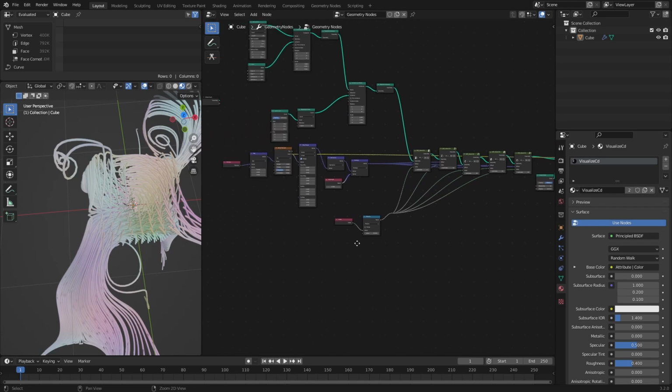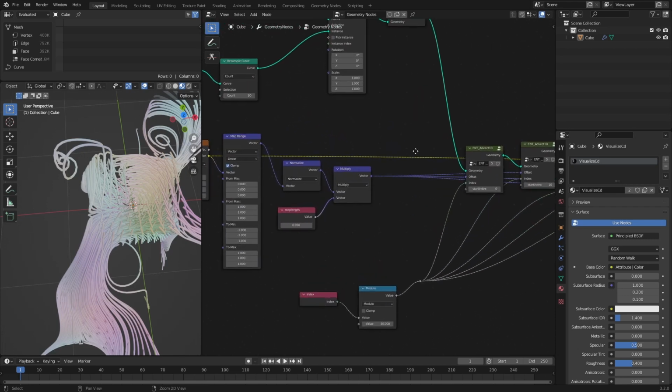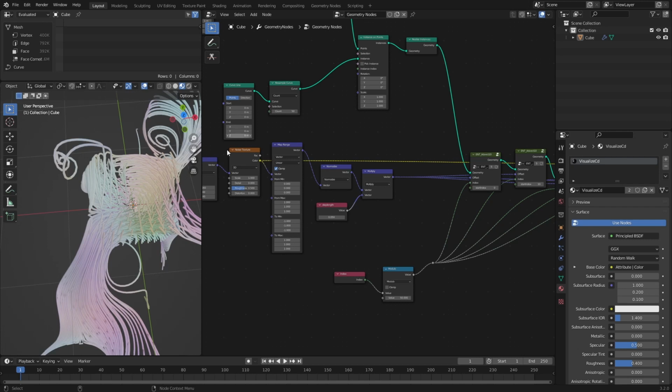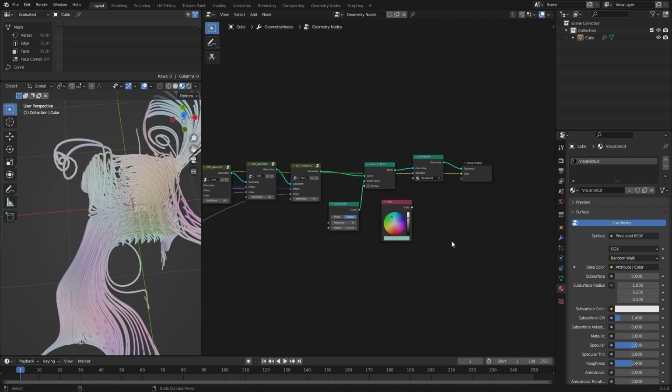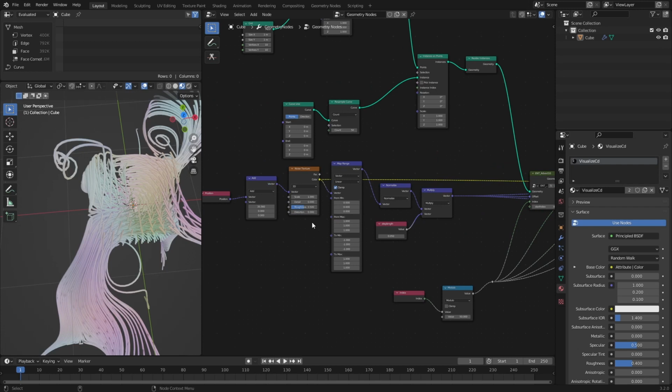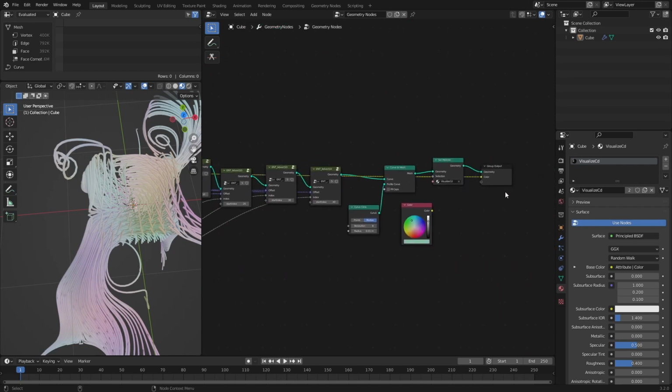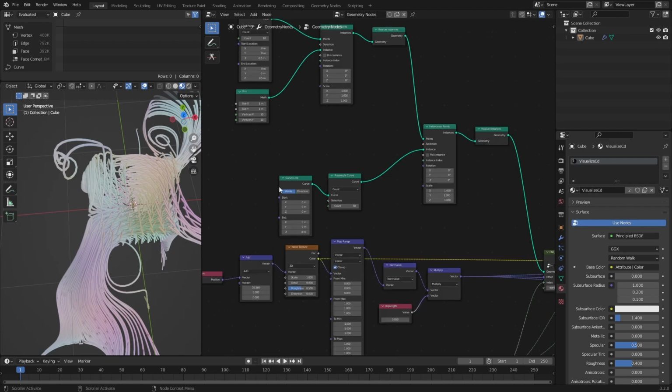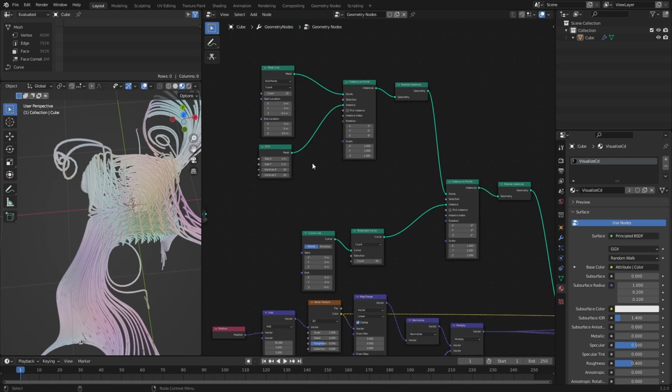To do this, we need a node that tells geometry nodes where to execute this color field here. At the moment, it is executed in this context. So the geometry port on the group output determines the context that the connected field, in our case this noise texture, is executed in. And because we have all the points here, the noise field is executed for all the points. We want to execute the noise field for all the points before we put the curves on them. So for the original points of these cloned grids here.